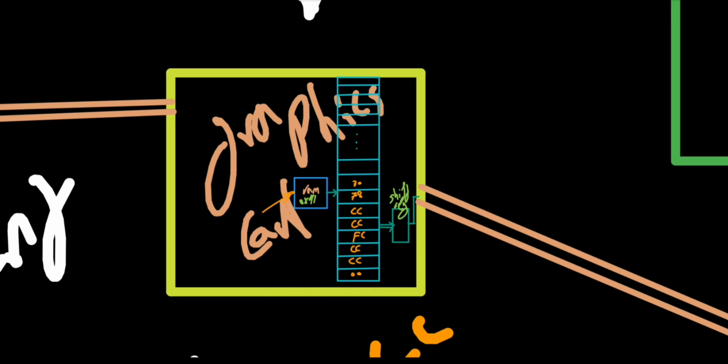Why do we need RAM? So that we could tell the graphics card what we want to be written on the display. We know that we want to write the value of A, but we also know that the computer doesn't understand anything called A. It understands zeros or ones. So A would have a number associated to it so that the graphics card would know what this A means. This value would be 0x41. We say this is the ASCII value of 41, or the code point of the A. So 0x41 means we would have 01000001.